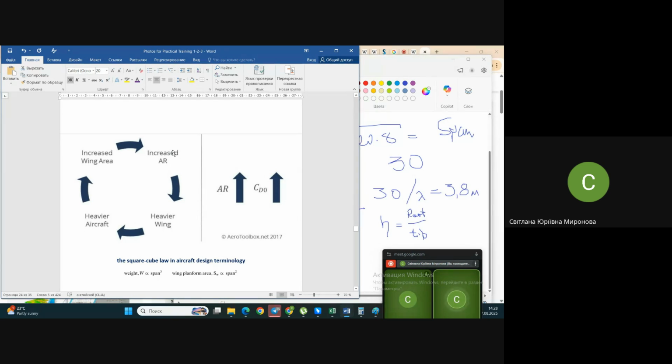And the real aerodynamic characteristics and performances of your aircraft as a whole, you might determine finally only knowing all the dimensions and all the shapes, when it has already been designed, at least by outer shapes, and creating a scaled model of your airplane. You may do a test in a wind tunnel. In this case, you will be aware of the real characteristics of the airplane and wing and stabilizer and so on, not earlier.